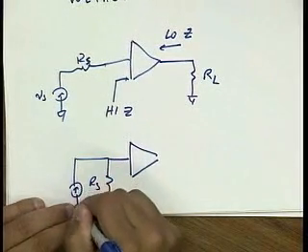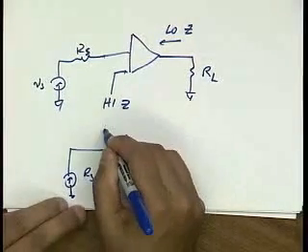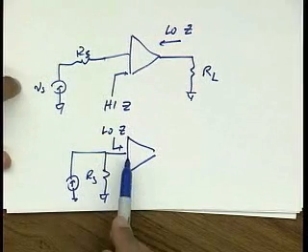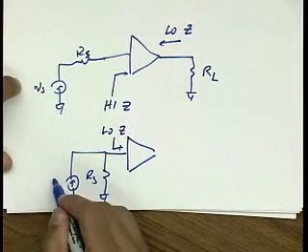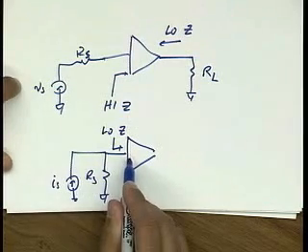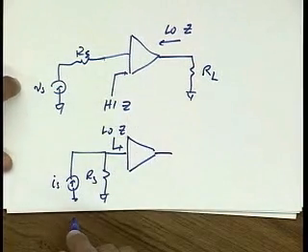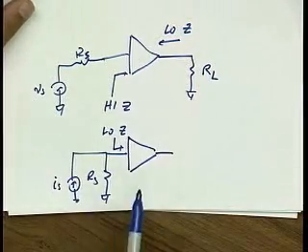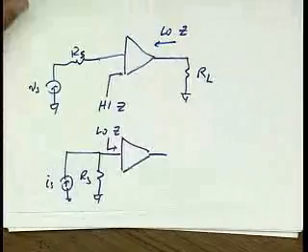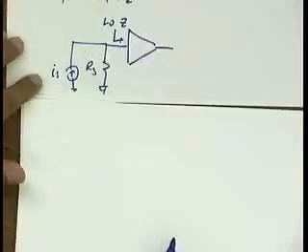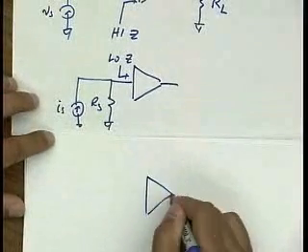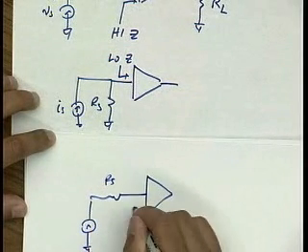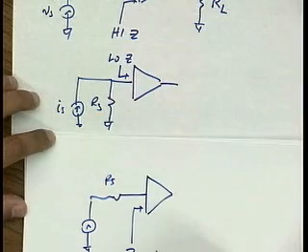So for a current amplifier, we like to see a low input impedance because basically we want this to be ideally a short. We want the entire source current to go into the amplifier and appear at the output. Now in this class, instead of having high or low input impedances, we're going to do something funny and design matched input impedances. In other words, if this is RS, we'd like the input impedance Zin to equal RS.